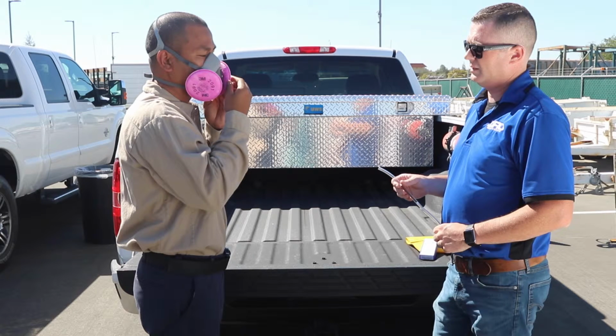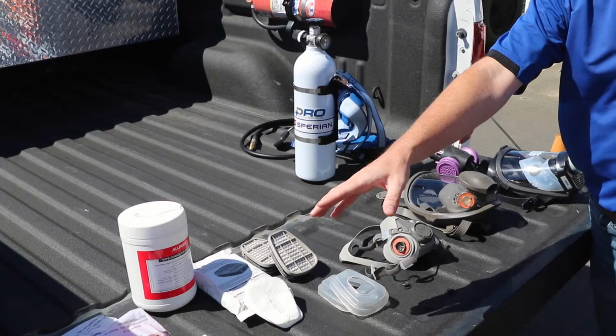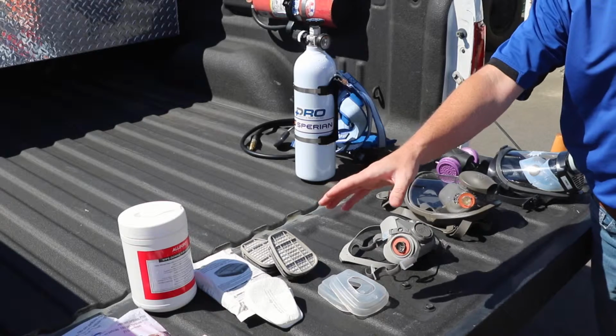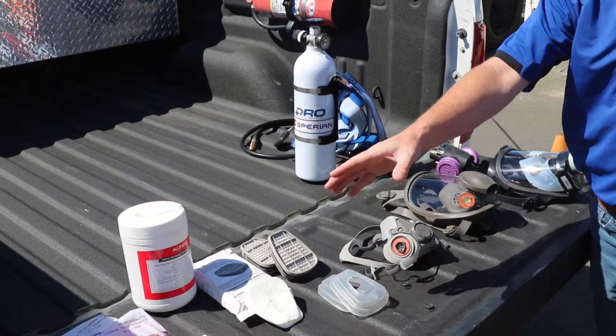The half and full face respirators are considered tight-fitting and allow for different types of filters to be used for different hazardous environments. The filters and canisters are an important part of these respirators. The filters are a component used to remove solid or liquid aerosols from the atmosphere. Make sure to follow the manufacturer's service time limit recommendations. Most filters have a service life indicator built into them. That is a system that warns you that the filter is nearing the end of adequate protection. The canisters and cartridges are containers with filters built into them that will remove a specific contaminant from the air passing through the container.